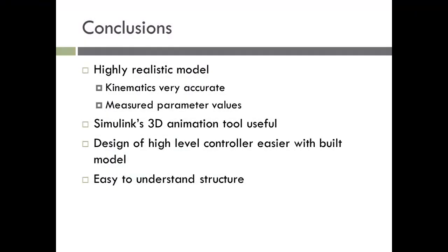The main goals of this project have been to model, control, and animate a quadcopter with Simulink 3D Animation. The model built is highly realistic, taking into account all the dynamic effects, even the gyroscopic ones, simulating every motor and inverter, with the parameter values measured from a real quadcopter. Matlab Simulink has been essential for implementing the whole project, especially the 3D animation toolbox, converting the result of the simulation from some plots to a highly understandable animation. The interpretation of the movement of the helicopter is much more intuitive than before, as a 6 degree of freedom system is not trivial to analyze.